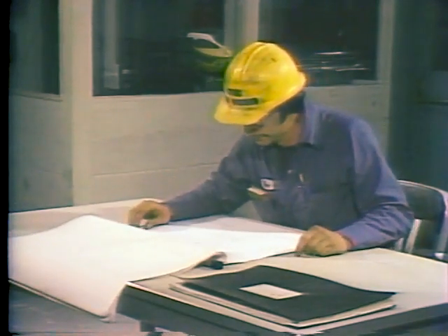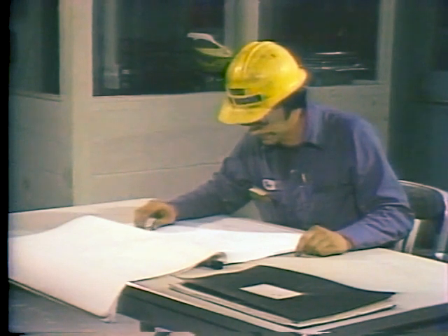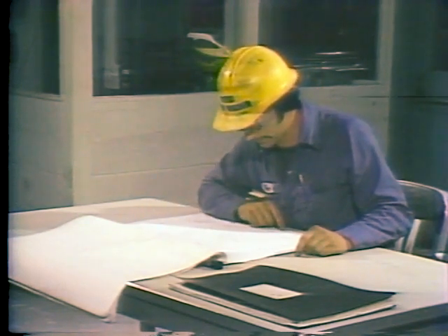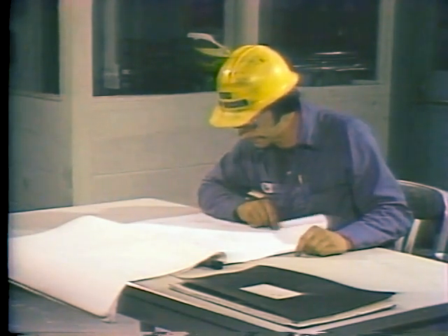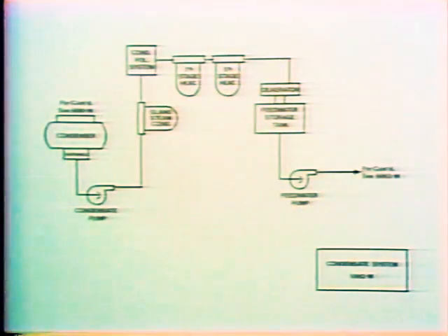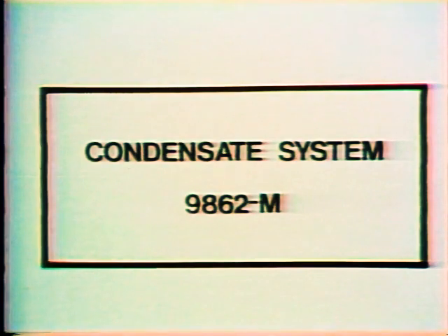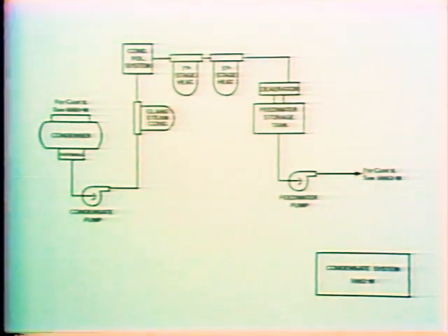Usually, one page of a P&ID will show all or part of just one of the many systems that make up a unit. So that you can identify which page goes with each system, P&IDs are usually titled and numbered. The title and number frequently appear in the bottom right-hand corner. The title and number are sometimes used to tell you where one P&ID connects to another.